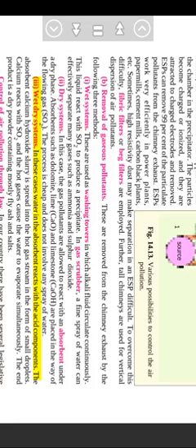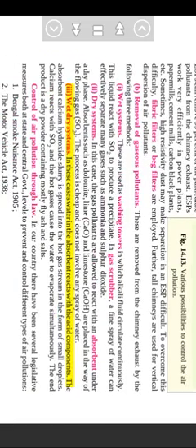3. Wet-dry systems. In these cases, water in the absorbent reacts with the acid components. The absorbent calcium hydroxide slurry is sprayed into the hot gas stream in the form of small droplets. Calcium reacts with SO2, and the hot gases cause the water to evaporate simultaneously. The end product is a dry powder containing mostly fly ash and salts.